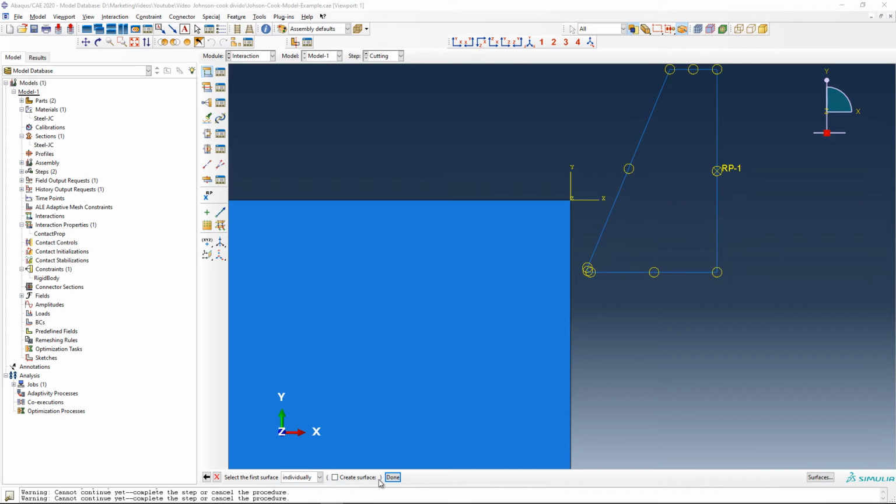So let's select the first surface, right here, and right here. Now, of course, we have to flip the surface so Abaqus can consider the normals in the right direction. Okay, let's flip it. We're going to select magenta.